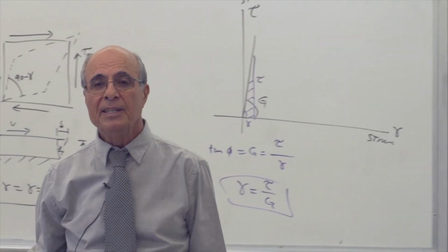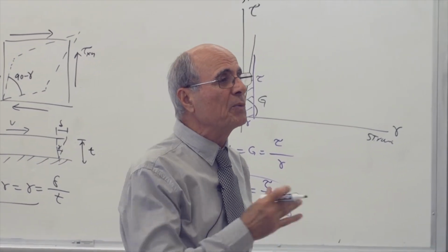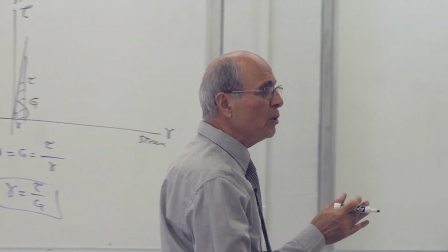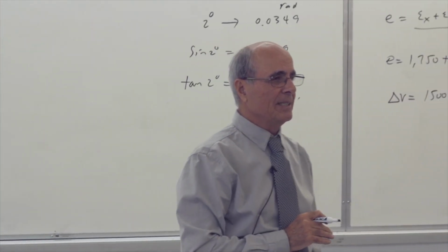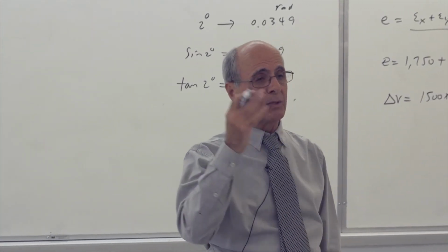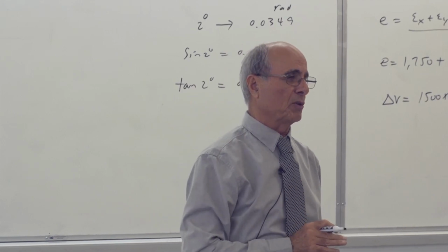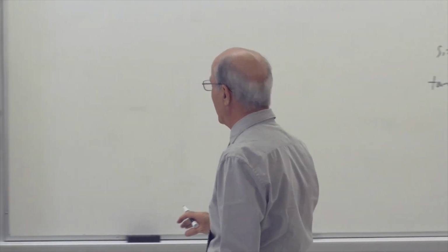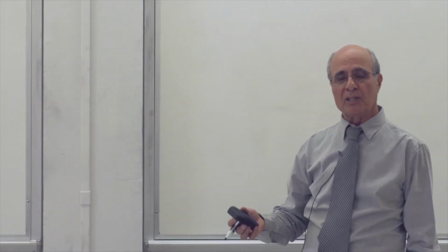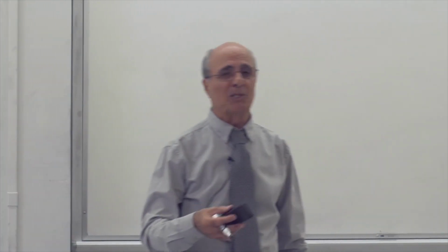Everybody, because theta or gamma is very small, so it is less than 2 to 2.5 degrees. That's what happened. These angles should be less than 2 degrees. If it's more than 2-3 degrees, then this formula doesn't work, so you have to use tangent. Everybody understand? And that's why they use theta in your solution manual. I hope some of you did understand it. I don't know, or read it somewhere, but some of you probably didn't.